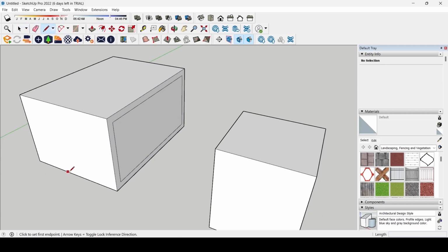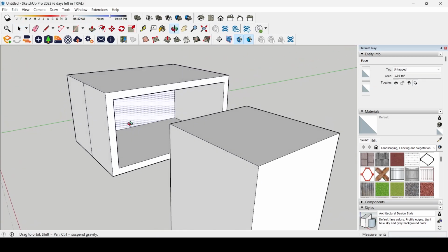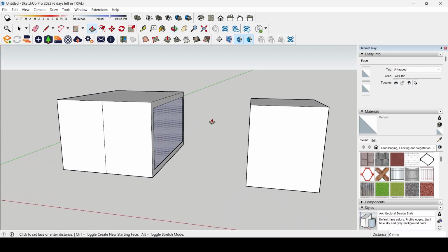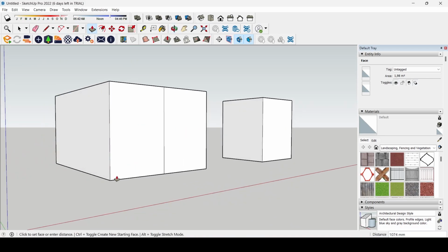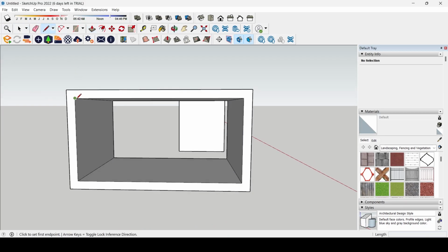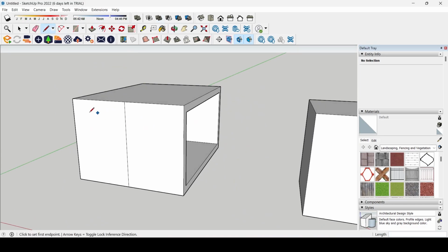You could also, if I drag a line from here to here, you can see now it has two faces here. And those I can pull and drag with the push-pull tool. And if I push it all the way down here and I snap to this point right here, it will make like a hole. It will just delete the face itself. And if I then just make a new line like this, it will make a new face. So that's a bit about the tools here.